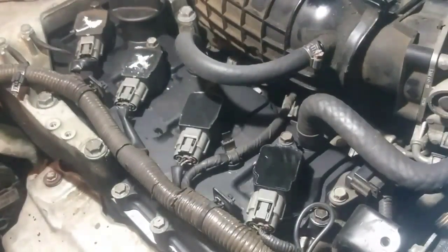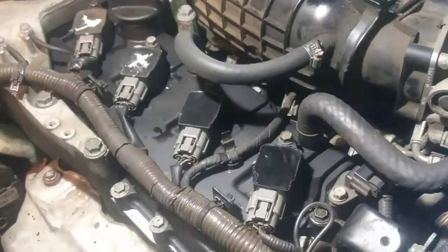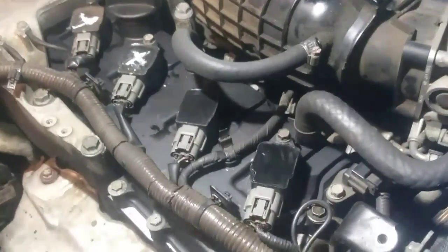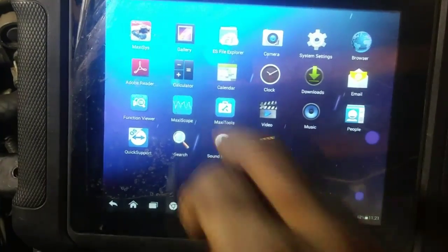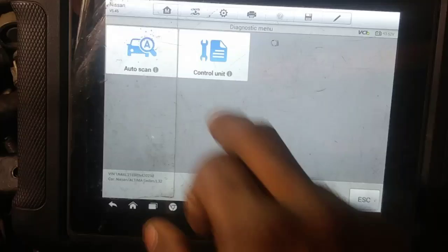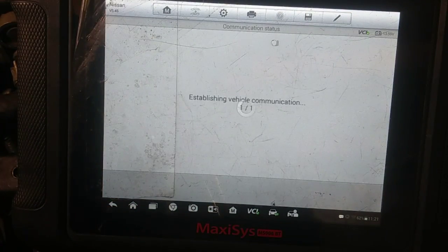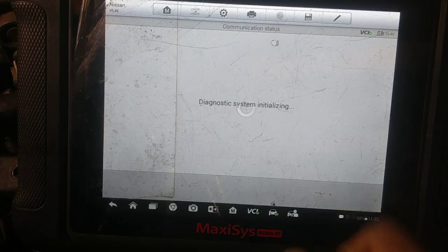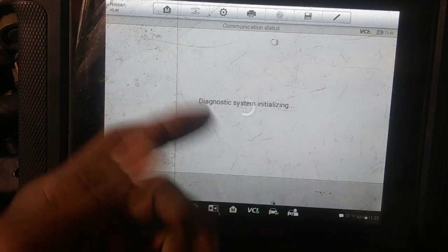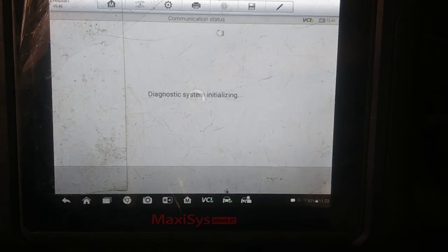So you know what, I don't know if you might feel it, so it might be a wise idea to look at that real-time misfire count here. So let's do that. That'll be the smartest move here to make. And I guess the downside is I can't pull up any additional information, so I can't show you RPM and misfire simultaneously. That's going to be a downfall, but we'll see.